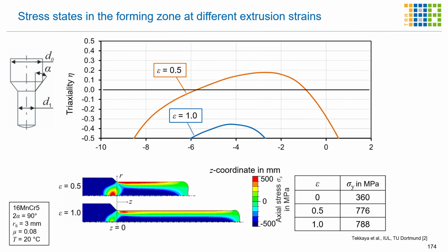For both cases, SEM measurements have already been performed. With a lower triaxiality, which represents the hydrostatic stress, we would expect that the damage evolution is in general lower or even nonexistent, leading to void closure mechanisms because we have a higher compressive loading state, which leads to void shrinking.